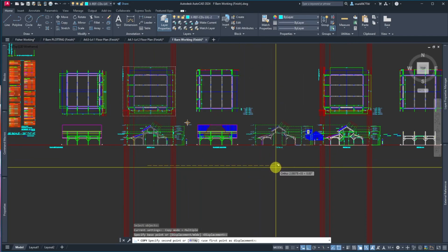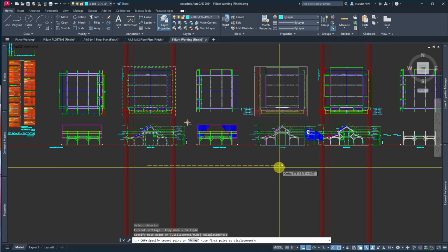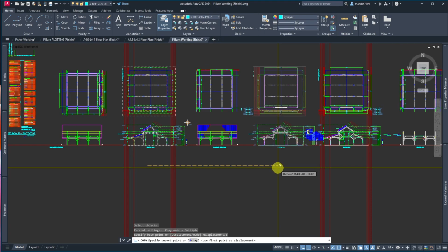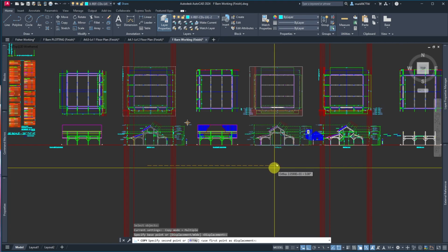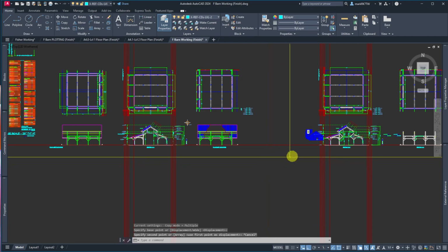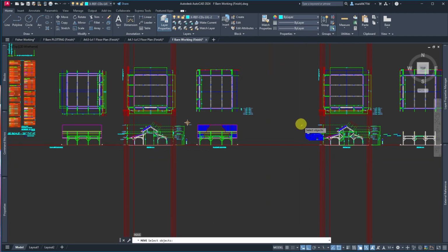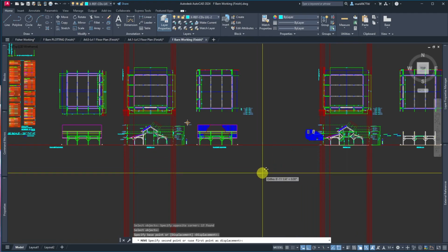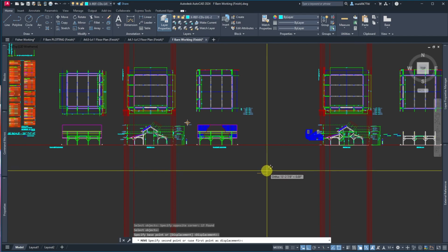And again, remember that window and stuff that are in the background there. They're not going to bug me because it's just a pattern. I do want the window, but that's going to be fairly easy to select, although I've gotten some text in it, aren't I? So let's hit escape. Let's not do that yet. Let's move this window for sure. Not as worried about the hatch, but I'm going to move the window over to where I can easily grab it later. And my ortho is on.